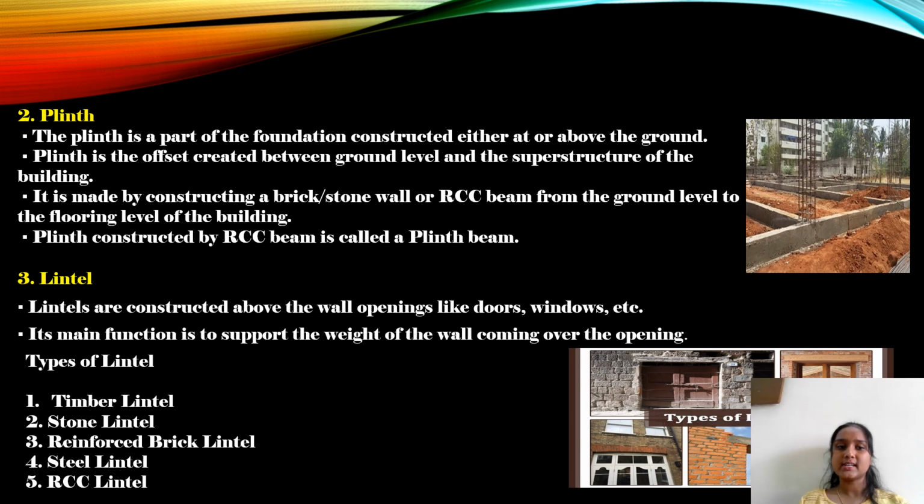Third one is lintel. Lintels are constructed above the wall opening like doors, windows, etc. Its main function is to support the weight of the wall coming over the opening. Types of lintel are timber lintel, stone lintel, reinforced brick lintel, steel lintel, RCC lintel.